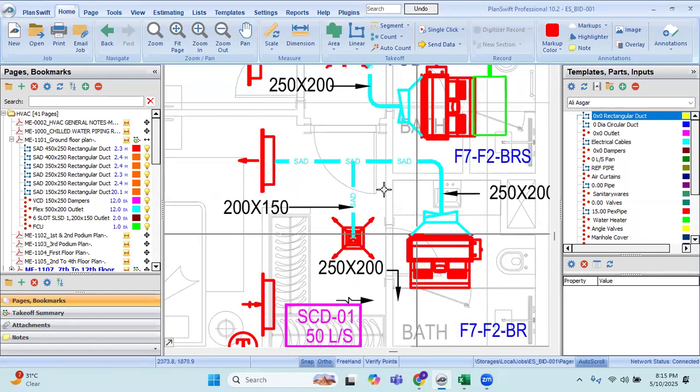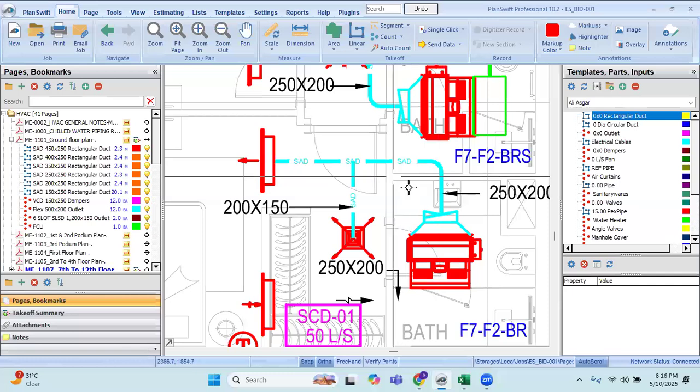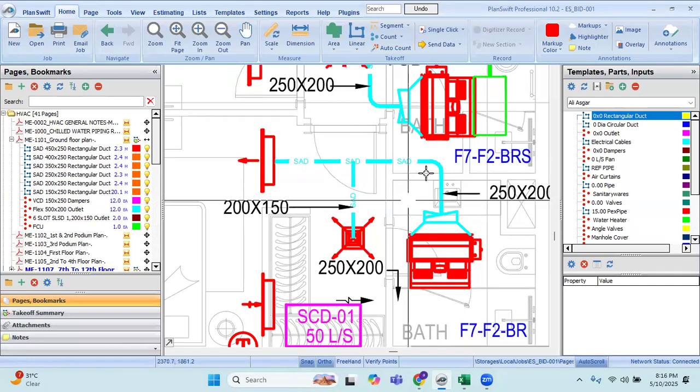So we need to take this quantity separately because there will be some extra insulation on top of this kind of duct. When you talk about a smoke duct in the parking space, we don't need any insulation on that. Okay, we need one fire rating insulation over it, but we don't need any insulation which will protect the heat from entering inside the duct. But for supply air duct, for air conditioning duct, of course, we need insulation. So that's why this kind of duct should be taken separately.